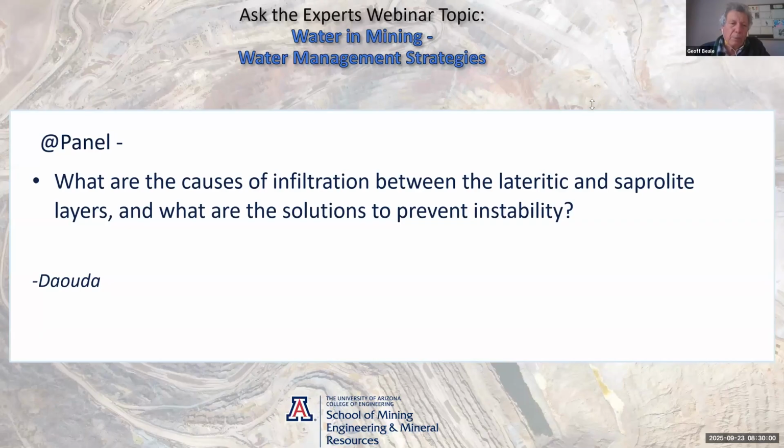If you can depressurize or dewater the permeable material or the fractures beneath the saprolite, then in most situations the saprolite will depressurize enough to give you 4, 5, 6, 7 degrees on your slope angle. Often, in cases where you have variable laterite, the saprolite performs better when it's overlain by laterite, because the laterite creates runoff and reduces the recharge for the saprolite and makes the depressurization more efficient.